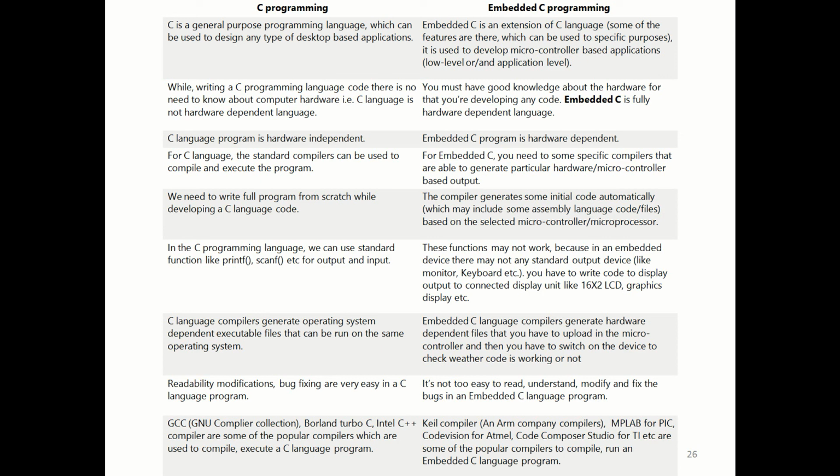They are different. So don't make any assumptions that printf, scanf as it is will work in embedded C. No, they don't work, because every company has their own way of dealing with the peripherals. Last 40 years, computer meant printf means the standard monitor, and the text also has a resolution of 80 by 25, something like that.